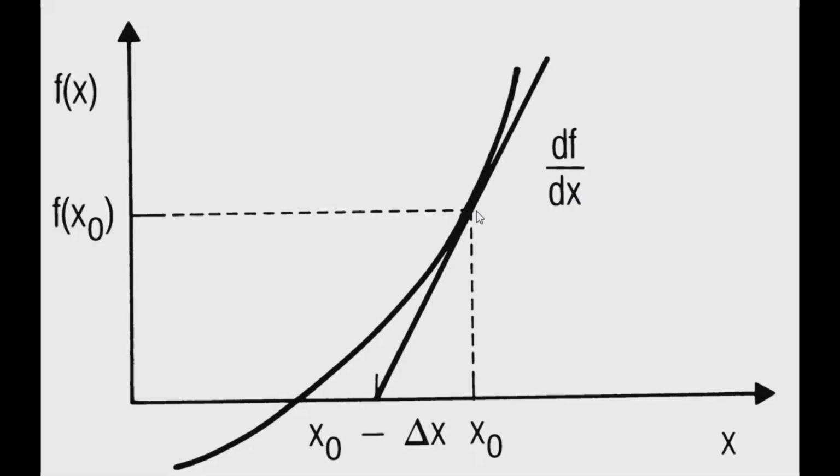And then instead of a scalar quantity like this for estimating the zero, we have a matrix equation that does it. So at each step in this iterative process, it turns out we have to solve this big matrix equation. The matrix is called the Jacobian matrix. So when you deal with harmonic balance, you'll hear terms like Jacobian quite a lot.